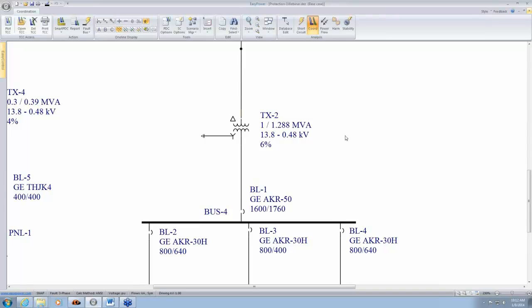As per the ANSI C57 standard, for dry type there are 2 categories, and for oil type there are 4 categories of transformers, and these categories are primarily based on the kV rating of the transformers. And so you can plot the damage curves for these transformers. I'm going to select this transformer and plot TCC.